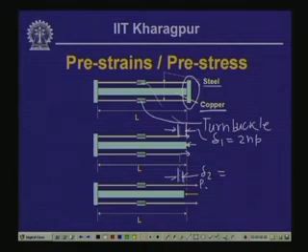If we call the force in the steel bar Ps, then delta 2 is equal to Ps times L by A E, or A steel E steel. So, this is the deformation that is occurring in the steel bar because of the application of the force Ps. Now, the compressive force which is applied to the copper bar, let us call that Pc. The deformation from this position to this position we call delta 3.